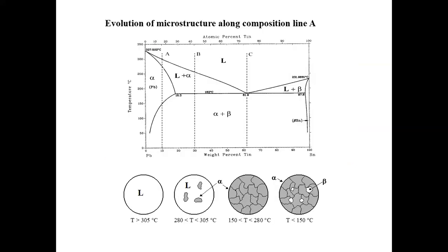Okay, so now when we move to the discussion of alloy, I think the first thing we'll refer to is a phase diagram, right? Because this basically collects all the information you want and you need in terms of the thermodynamics and phase transformation for an alloy system. Okay, and this is a very familiar phase diagram. This is the lead-tin eutectic phase diagram. I hope we still remember this guy, right?